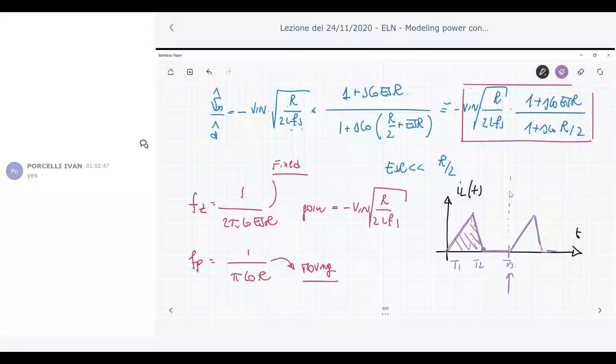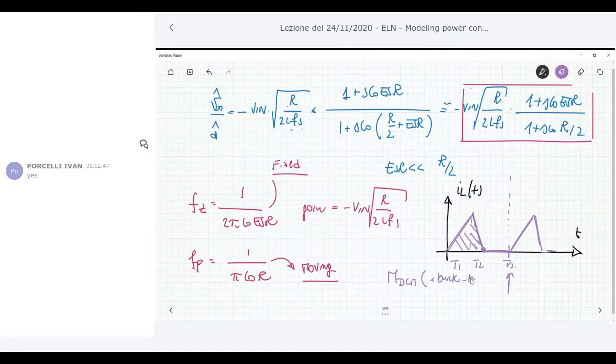We computed the energy in the charging phase of the buck boost, and then we said that since all this energy, which is acquired during the charging phase, is discharged in the successive phase, we are able to equate the charging energy with that which is discharged and to find out the conversion ratio. Remember, look at that slide, the way we derived the conversion ratio in DCM for the buck boost, because we exactly employed some energy considerations.